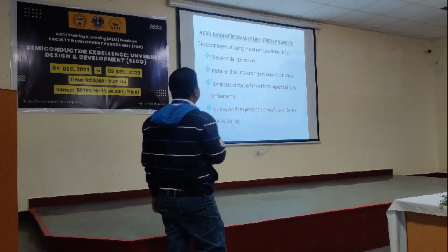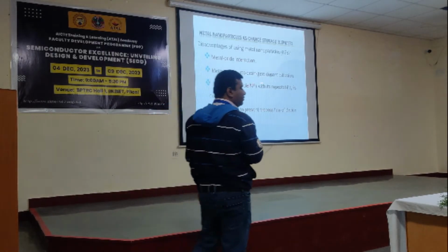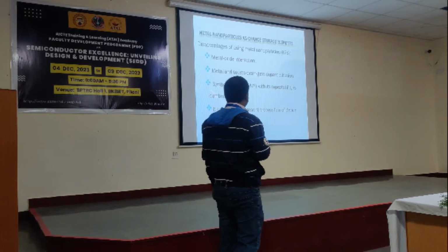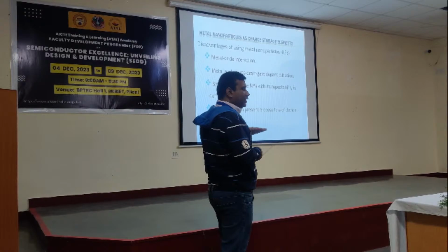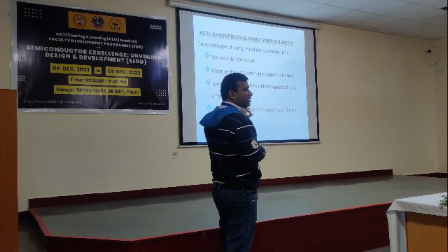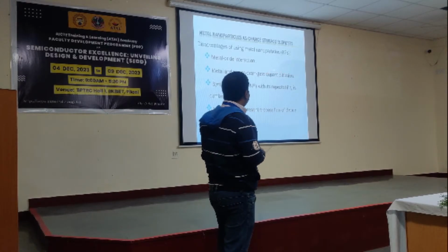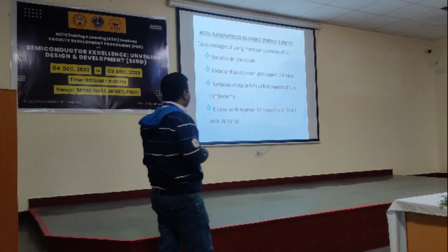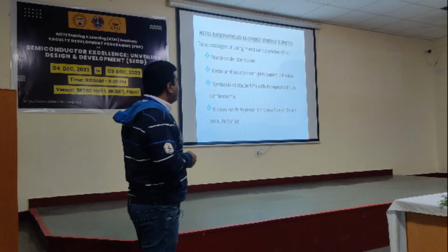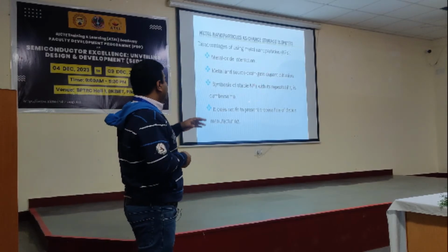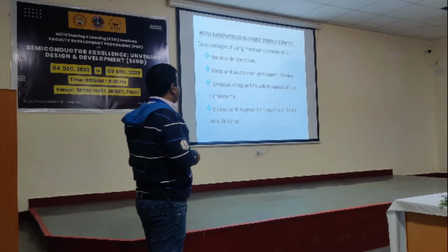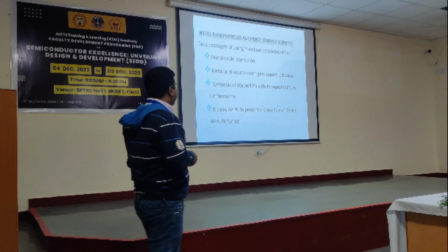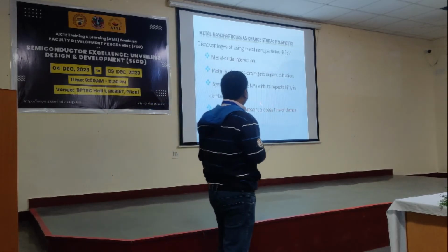But use of silver nanoparticles leads to several difficulties. In a metal oxide semiconductor, the oxide will react with the metal nanoparticle. In some cases, the metal also acts as a dopant in the source and drain regions. Again, synthesis of stable nanoparticles is a very cumbersome job. It does not fit the process lines of device manufacturing technology.